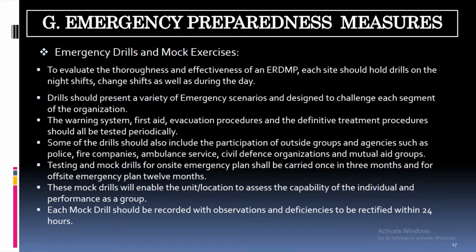Then testing and mock drills for the on-site emergency plan shall be carried out once in 3 months, and for the off-site emergency it should be around 12 months. These mock drills will enable the unit or location to assess the capability of the individual and also the performance as a group. Each mock drill should be recorded with observations, and deficiencies should be rectified within 24 hours.